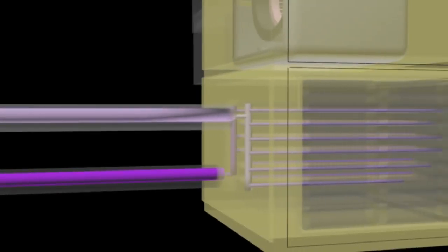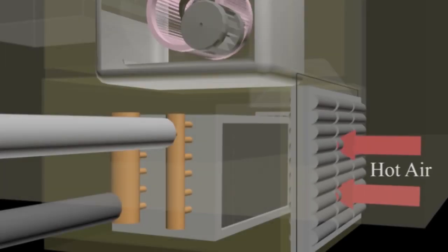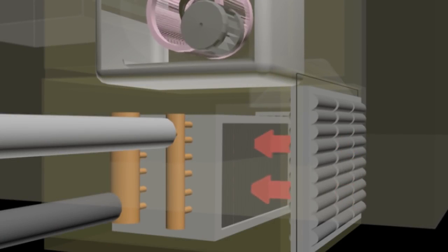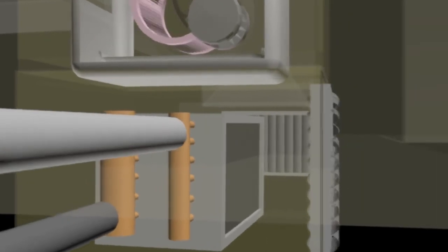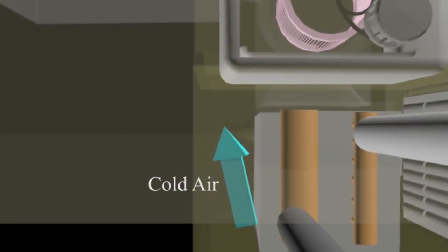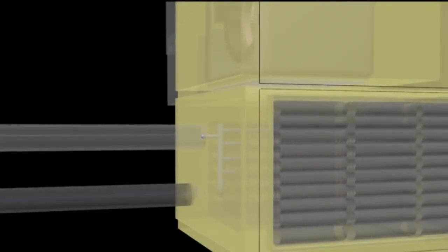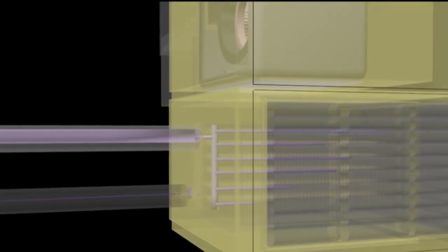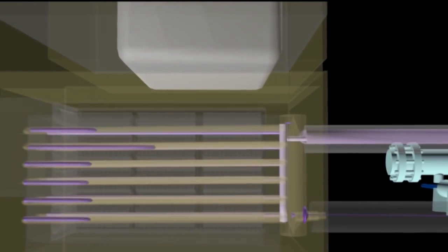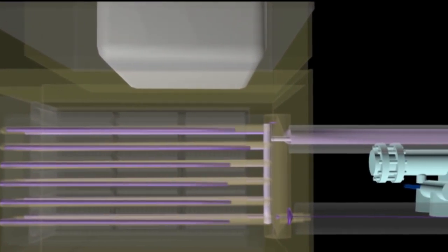In air handling units, chilled water will then pass through the cooling coil. In the cooling coil, the hot air will go through the cooling coil and switch to cold air due to the heat transferred to chilled water. Cooling coils commonly used in this system are tube and fin. After absorbing heat from the hot air, the chilled water will be known as chilled water return. Normally the chilled water return pipe will be colored with light blue.